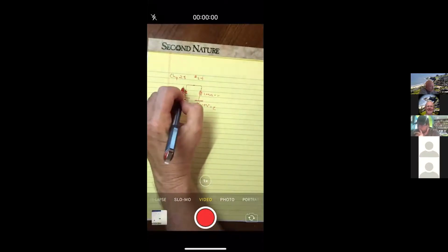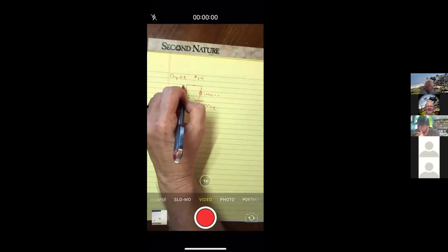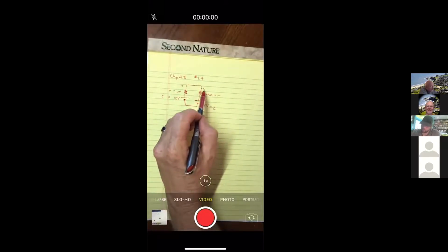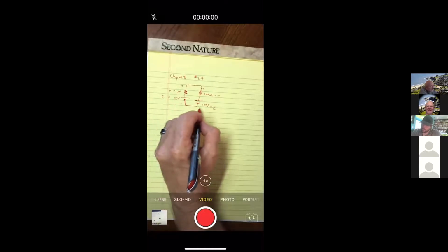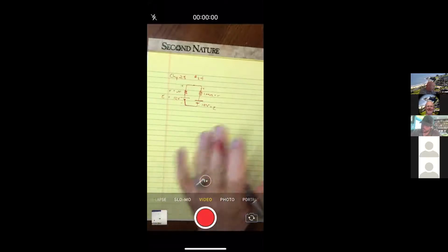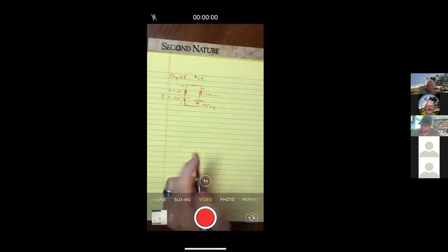And so what you've done is you've taken the positive side of the good battery and put it on the positive side of the dead one, and the negative of the good one on the negative of the dead one, okay? And if you just left it there, you would essentially be charging up that battery.